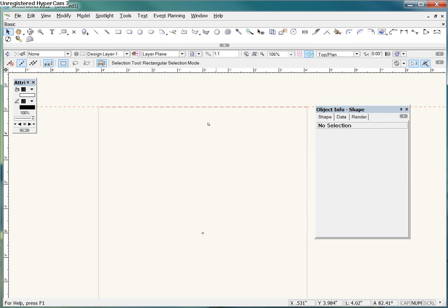All right, it's time to actually start drawing something. Let's make a door flat, our first measured drawing. Let's use some of the basic tools to construct a door flat in scale and throw some dimensions on it. Actually start using some of these tools with a purpose in mind, to draw a 4-foot by 8-foot door flat with a 3-foot by 7-foot door in the center of it.